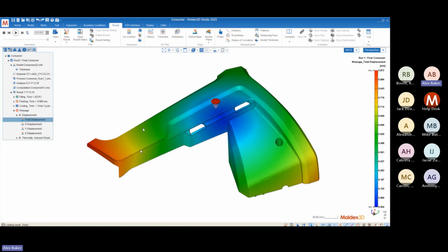If you look at the warpage first, you're going to be biased and you're just going to be going on a wild goose chase to find out where that warpage might have come from. Instead, you should be going through the filling, packing, and cooling to get a premonition of what the warpage results should look like. And if those warpage results are not what you expect, now you have a more educated result interpretation methodology to go back and figure out why that might be the case.